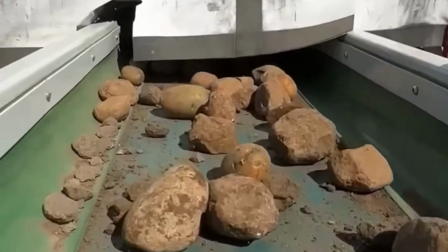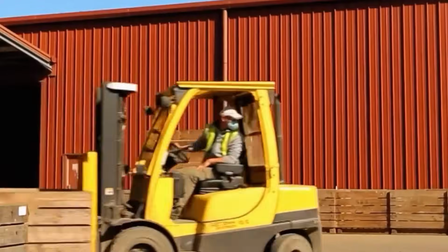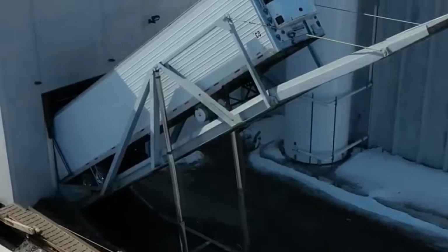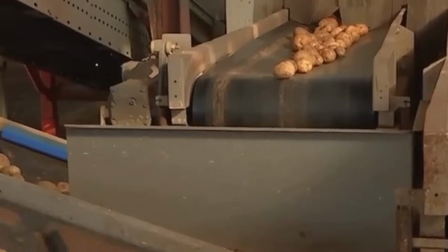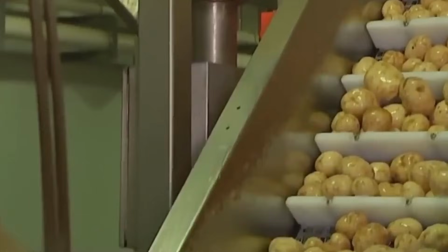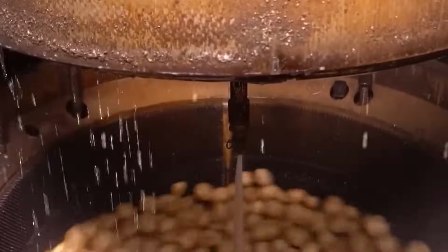Here, pre-printed film is formed into a tube, sealed longitudinally, and sealed at the bottom to form a pouch. The chips are dropped in, and the top is sealed to complete the package. The seal jaws also cut the film to separate each bag. Each package passes through a check weigher to verify total mass and a metal detector to ensure food safety. Out-of-spec packages are automatically ejected onto a rejection lane. Accepted packages move to high-speed collation and case packing systems.